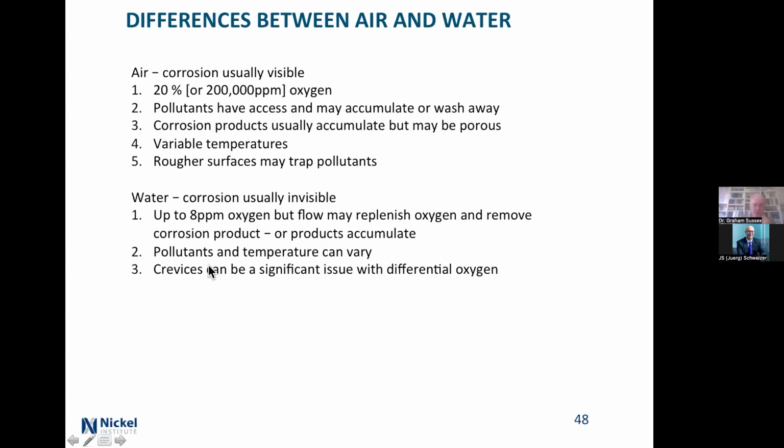And the pollutants and temperature in the water can vary. You may have hot water, you may have cold water, you may have raw water, you may have distilled water. And crevices can be a really significant issue because underneath the crevice, you have low oxygen. Outside, you have high oxygen, and so you can drive the difference between those two.